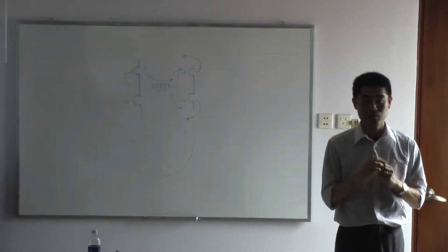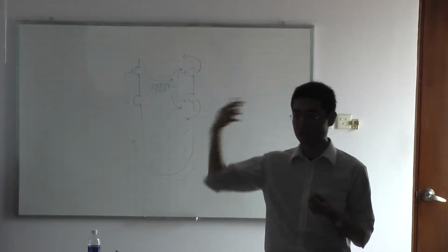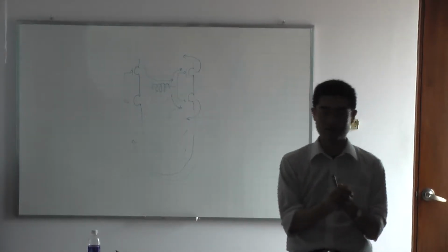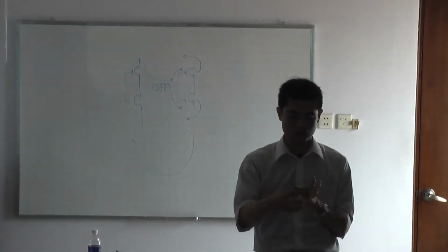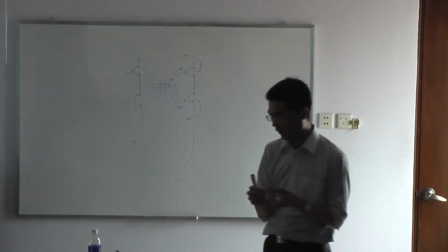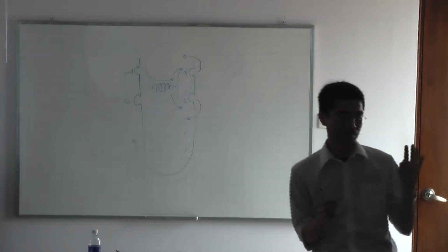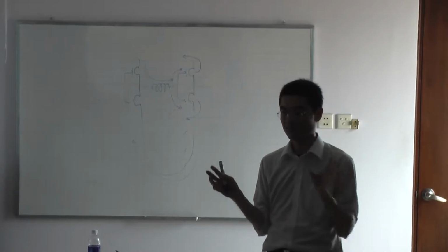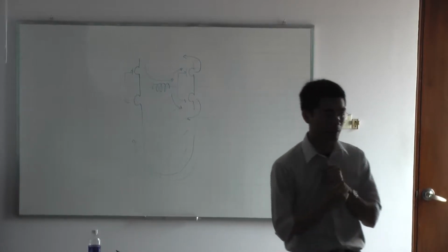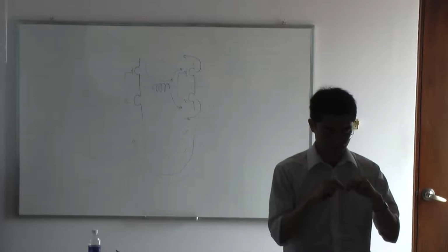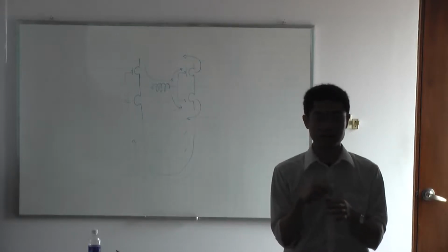And connectors. When we measure the device, we have to connect the measurement device with your LSI chip. Maybe you mount your chip on the board, and you use many kinds of connectors. We have many types of connectors. The first one is the header pin, and with header pins we can have many pins in the same area.